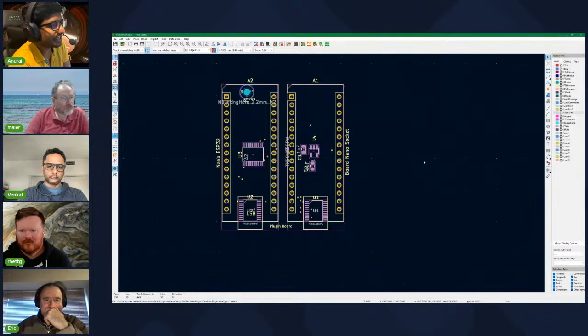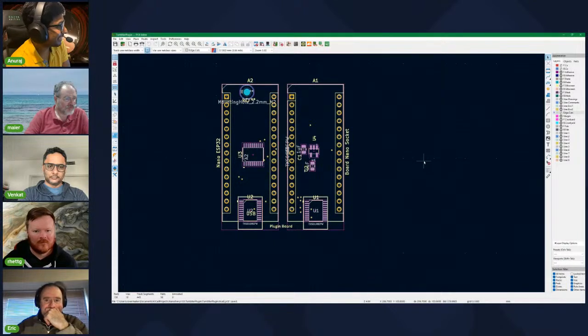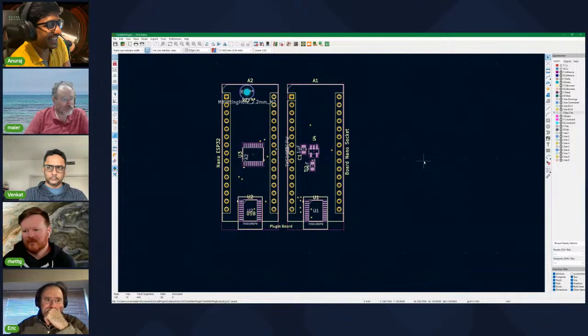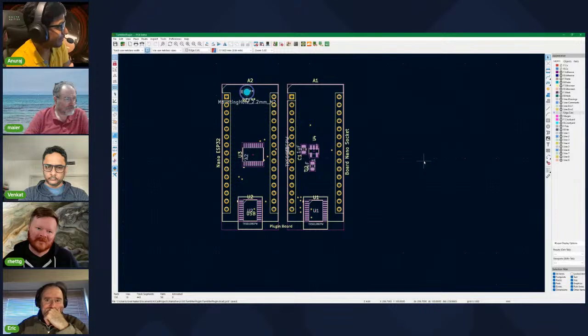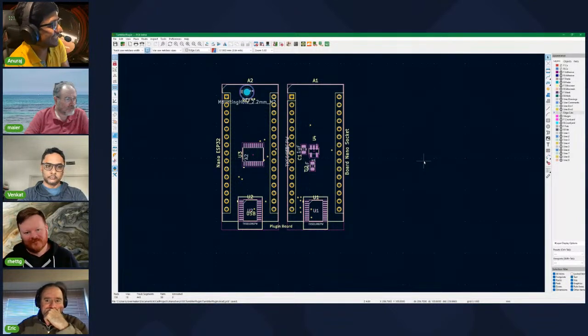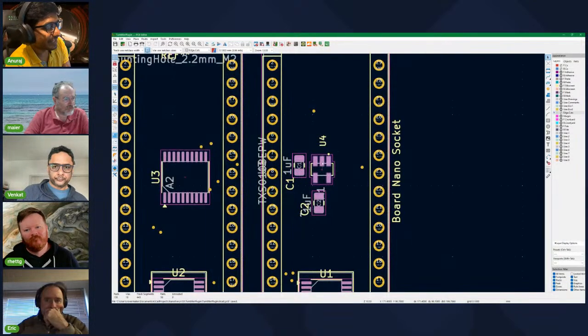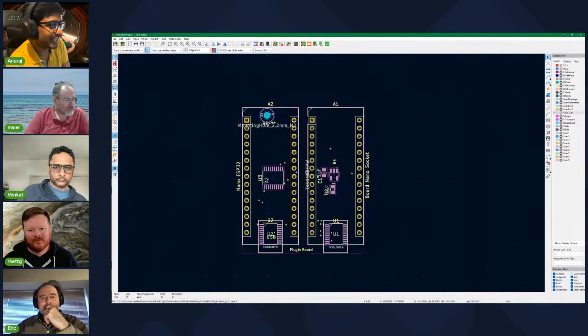So I had to go through this cycle 4 or 5 times, because sometimes the footprint would not be available, sometimes JLCPCB would not have the component, and sometimes the buck converter company would say it is an obsolete component, don't use that. So there are two or three places where you have to check that everything is working. Finally I settled on this Diodes Incorporated part, which had enough supply for manufacture, and I got the footprint from SnapEDA and placed it here.